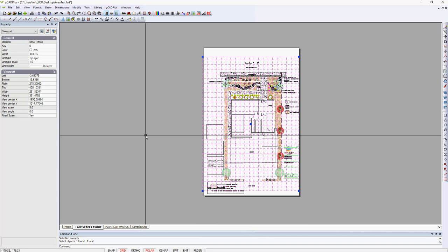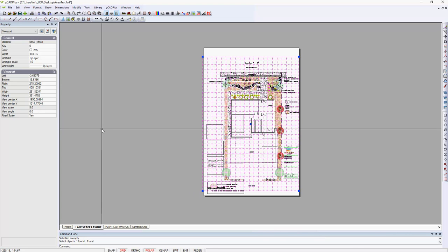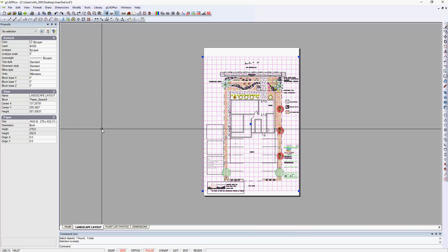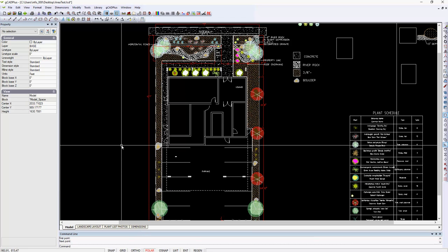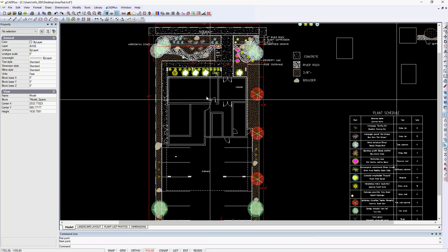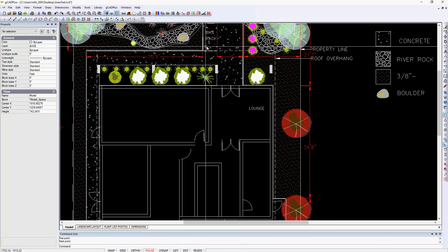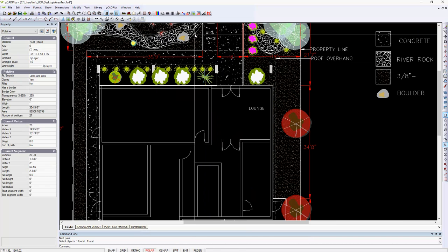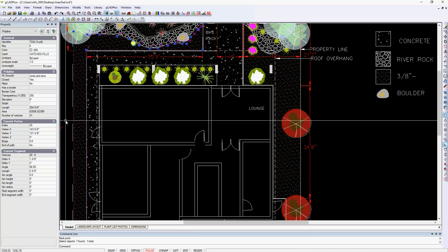Now in the US we would use 1 to 96 or 1 to 48, which will give a value in that view scale that has got a decimal place in front of it. So this, to fix up any area calculation, be it selecting some sort of polyline here, and if I come down there, the area will be 83506 square feet.